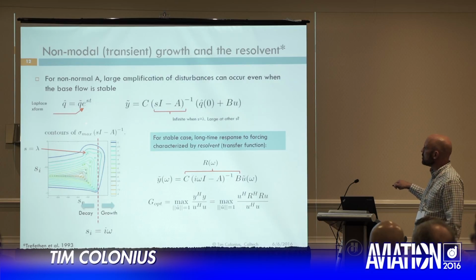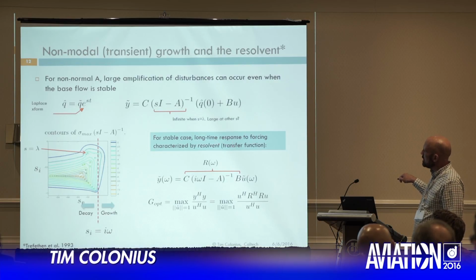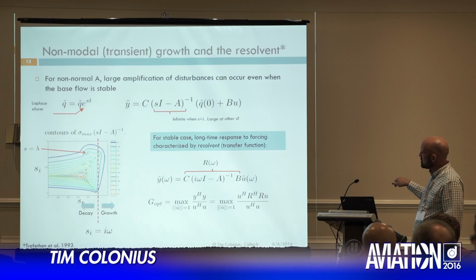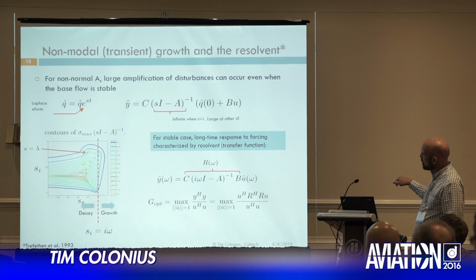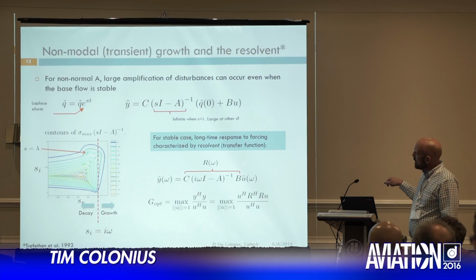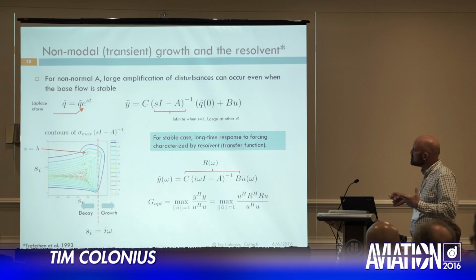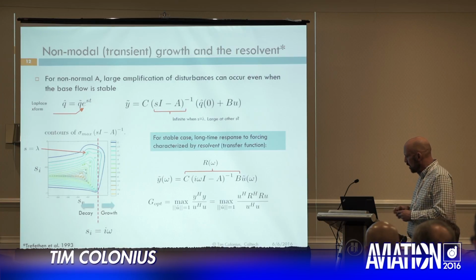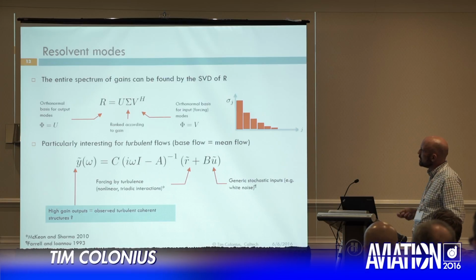That real-time frequency characterizing the system here is a concept called the resolvent. When we write this along the imaginary s-axis, I've simplified it here, y of omega. We call this the resolvent operator. This is interesting because it tells us, in a sort of steady-state or stationary fashion, how inputs are amplified into outputs of the system. It's basically a transfer function, but a multidimensional one.